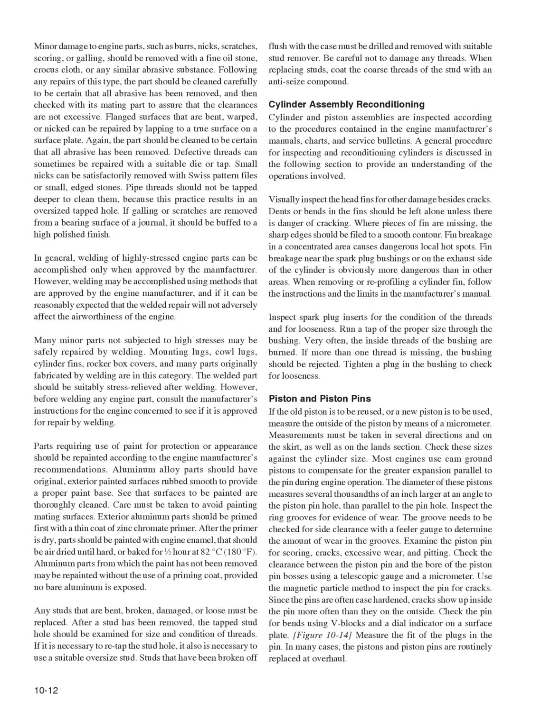Flanged surfaces that are bent, warped, or nicked can be repaired by lapping to a true surface on a surface plate. Again, the part should be cleaned to be certain that all abrasive has been removed. Defective threads can sometimes be repaired with a suitable die or tap. Small nicks can be satisfactorily removed with Swiss pattern files or small, edged stones. Pipe threads should not be tapped deeper to clean them, because this practice results in an oversized tapped hole.